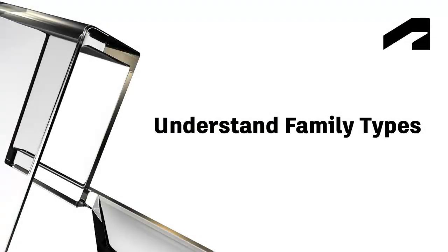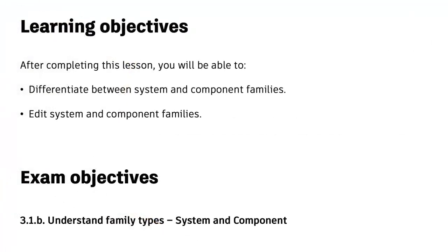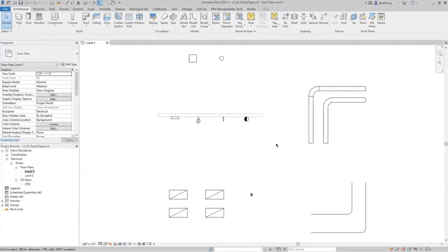In this video, we will cover differentiating between system and component families and editing system and component families. In this project, several elements have been placed. It's important that you understand whether an element is a system family or a component family.